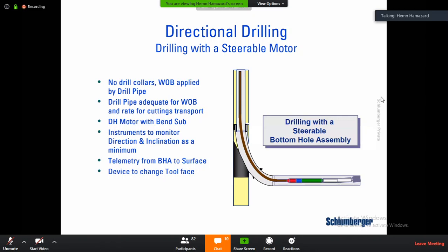Okay. The Kelly, like I said, is less efficient compared to the top drive. Nowadays, Kelly is very rarely used, and usually it's used for shallow wells, like in Kurdistan, as far as I know, in Khurmala, because the wells are shallow. With the top drive, you can rotate from the top anytime. If you have any hole problem, you can rotate. You can back ream while you are pulling. Secondly, you can drill a full stand with the top drive. This is the main thing for the top drive over the Kelly system, and it takes way less time to make a connection.